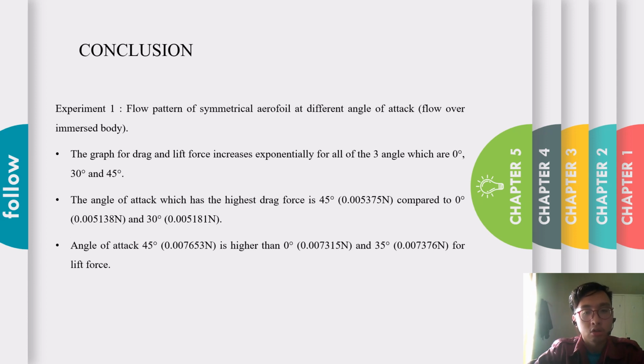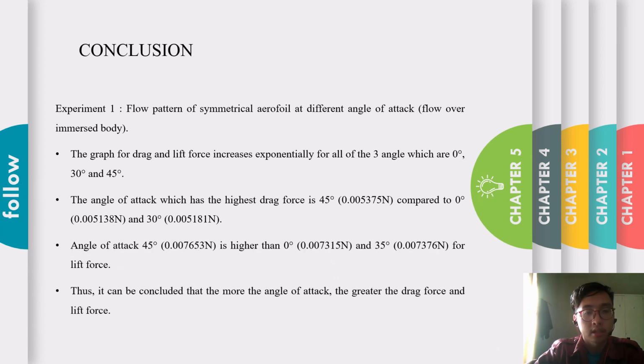0.00765 Newton, compared to 0 degrees, 0.007315 Newton, and 35 degrees, 0.007376 Newton. So it can be said that the greater the angle of attack, the greater the drag force and lift force.